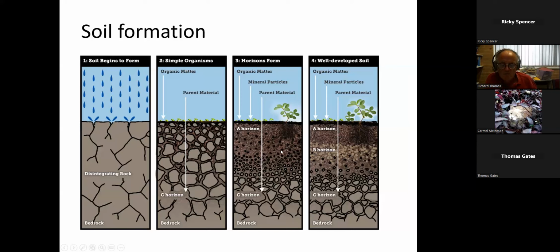Ideally, you'll move to get the A and B horizons in here, where you'll get residual rock in this area, but this, what we're now going to call the A horizon, we're going to call topsoil, would contain high organic content, and the minerals in here will depend on the bedrock and the broken down rock of the C horizon.